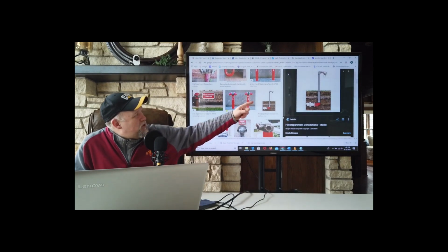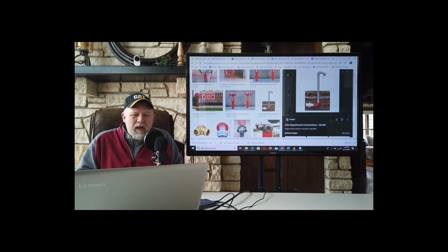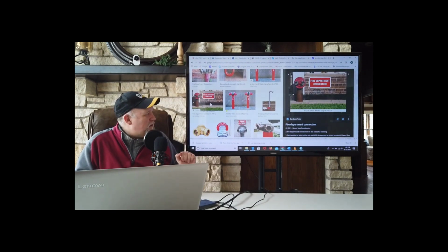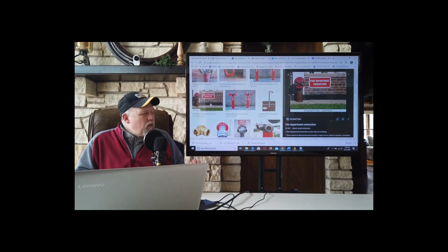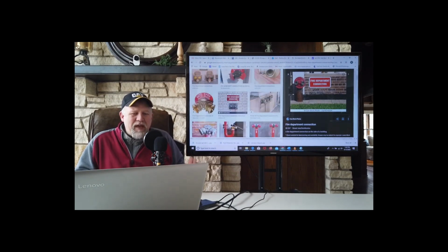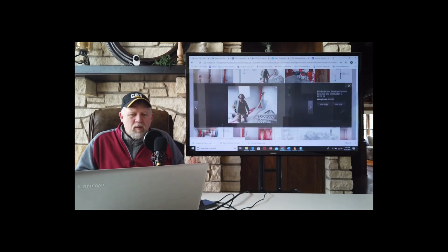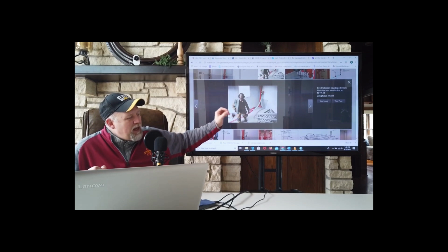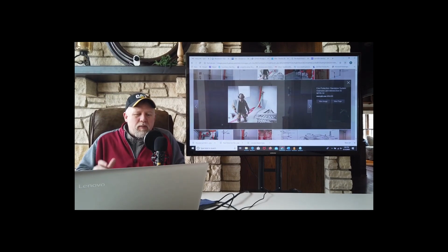Here's one that is just sticking out of the ground. It would probably be fairly close to a building. But the way this works is the fire department rolls up, connects to this hose connection, connects to a fire hydrant. They will use the pumper truck to boost the pressure of the existing system. If that's a standpipe, fine. Once the hoses are connected, we've got city pressure, but the pumper truck is going to increase the pressure of that water as well. So then when they run in, they're going to have even more water pressure than they normally would have.